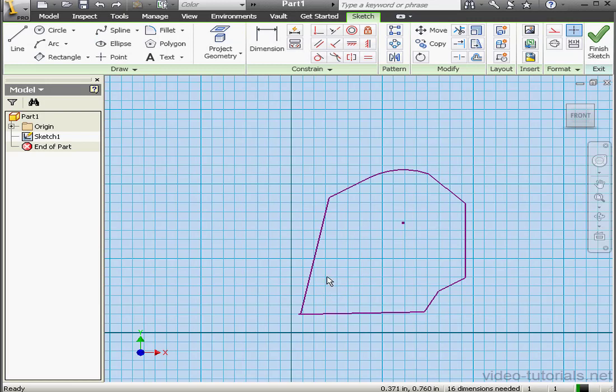In this case, when I drag the line just a little bit down, the resulting gap allows me to easily add a coincident relation. Let's unselect the segments in the graphic area by clicking outside. And let's click on the coincident relation up on the Constrain panel. Select the 2 points, right-click, and Done. Now if I grab and drag this line, it's clear that I've got a closed profile.